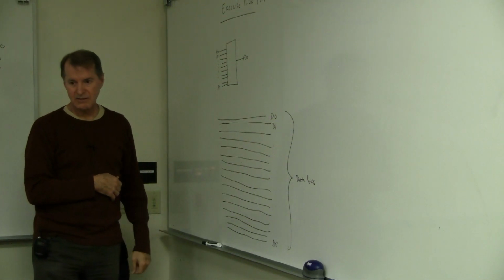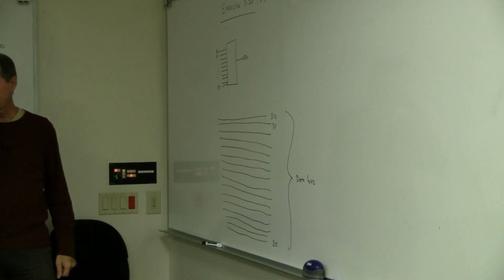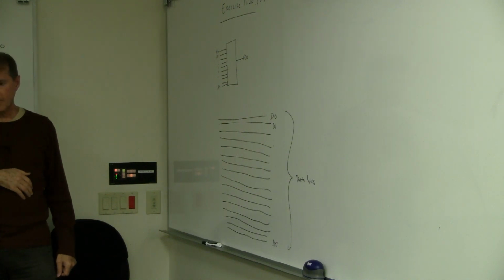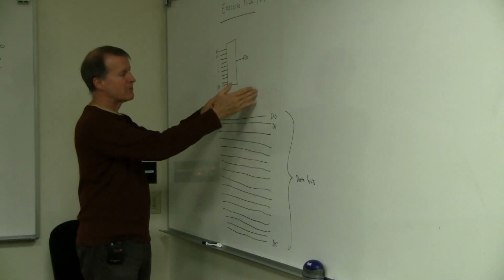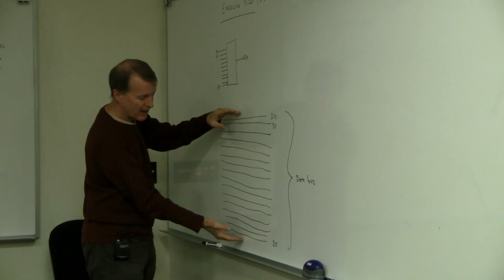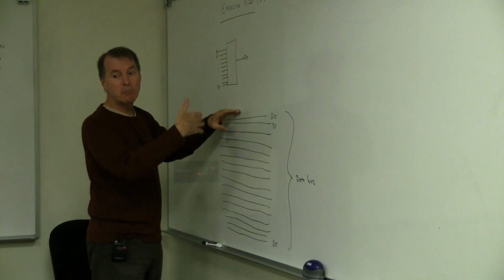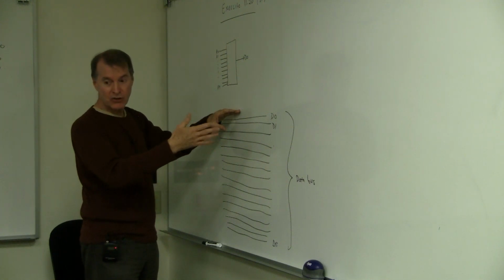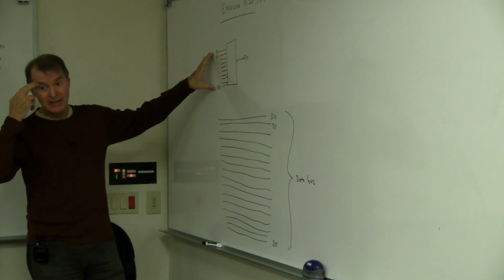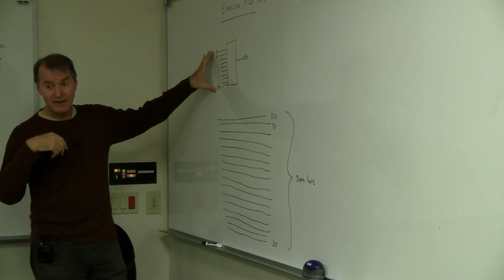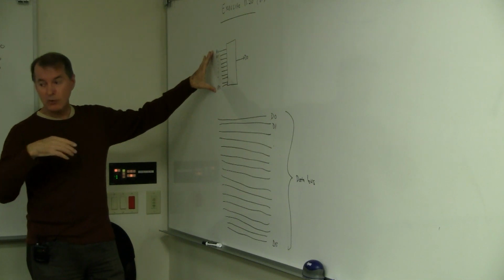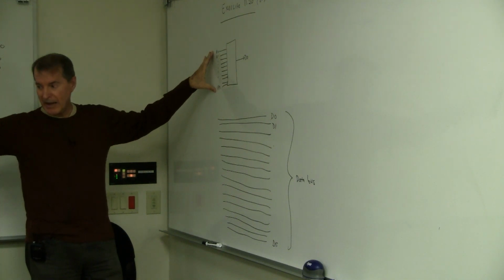I have more trouble understanding how you know that's the smallest number of bytes of memory. Because that's the minimum number of chips that you need to fully populate this. You could have more, sure, if the address bus is bigger than 10 in this particular example. If it's bigger than 10, then you would go to the memory map.